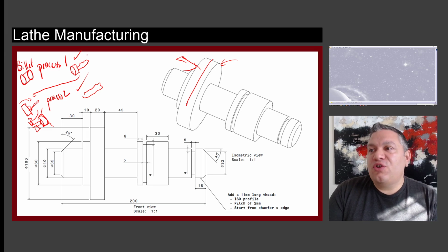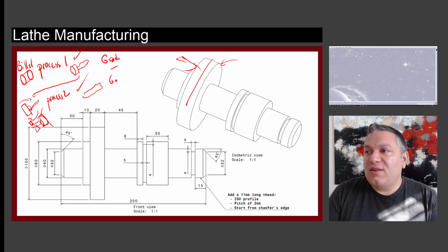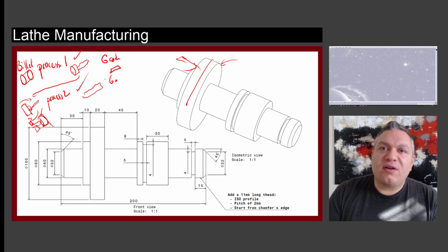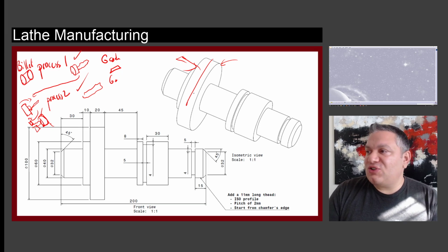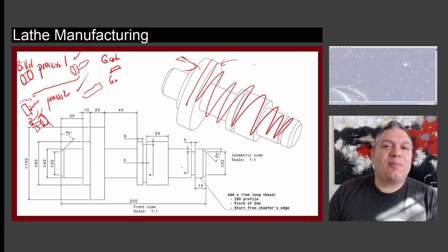At the end, you're going to have two G codes that are going to run on the machine, or you can even have one code that has a pause between them that asks the operator to flip the part, verify the reference, and so on. For us, we're going to have two G codes. We're going to suppose we are doing mass production. Like this whole portion gets done on a part.